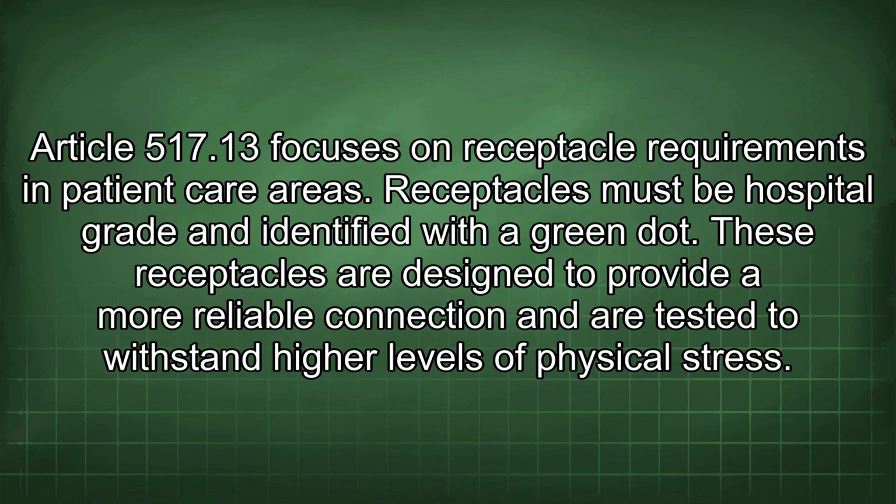Article 517.13 focuses on receptacle requirements in patient care areas. Receptacles must be hospital grade and identified with a green dot. These receptacles are designed to provide a more reliable connection and are tested to withstand higher levels of physical stress.